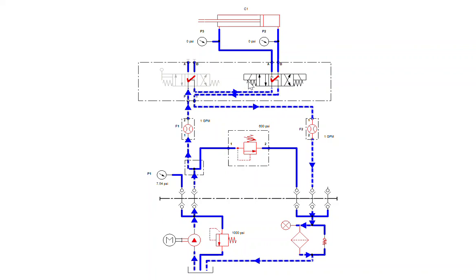And in this case, we're using this 3-position 4-way tandem neutral position, solenoid operated, spring-centered directional valve, operated by a joystick that energizes these solenoids to shift the valve and make the cylinder move. There's the lever operated valve sort of grayed out because the oil comes in, it goes through it, and it's really just part of the flow path, so it's not really part of the circuit. Its A and B ports aren't connected. So essentially, we can just bang this cylinder back and forth using this directional valve by energizing the coils.